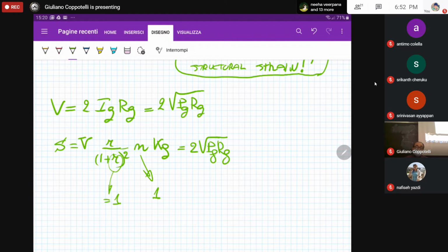If you remember, there is a summation with a change of sign of the changes of the resistances. The change of resistance of strain gauge number 1 is including both the physical strain and the temperature strain.